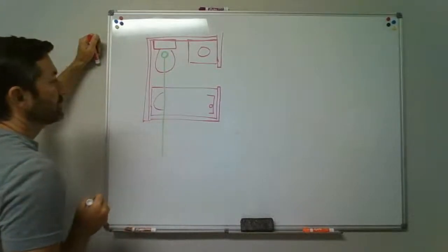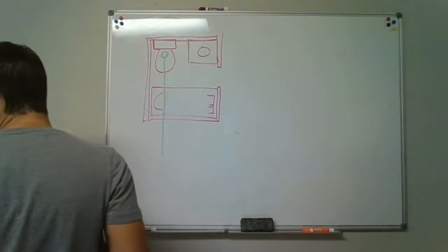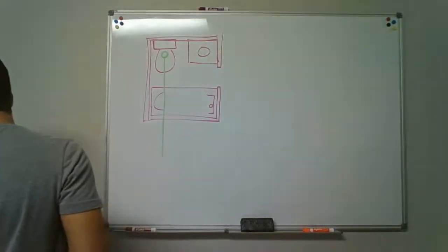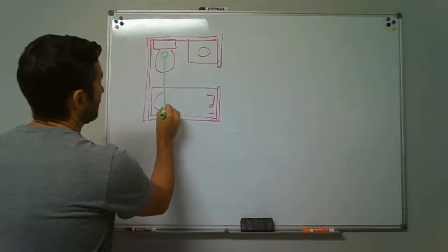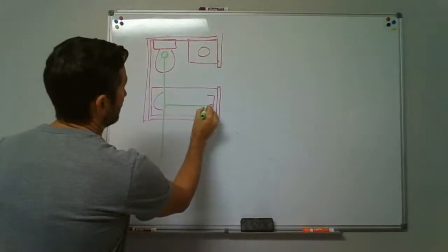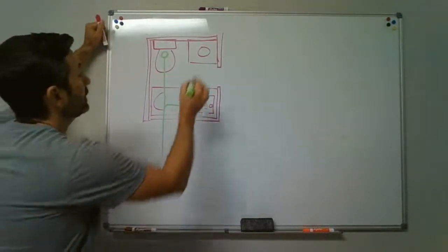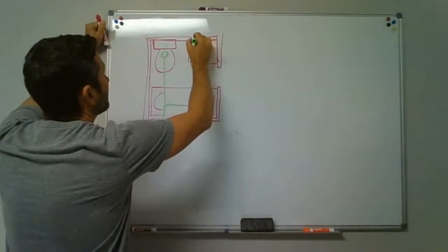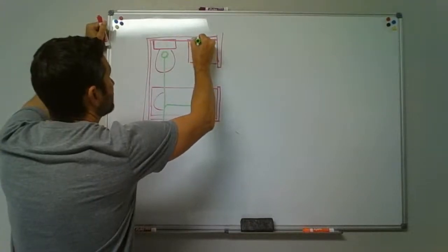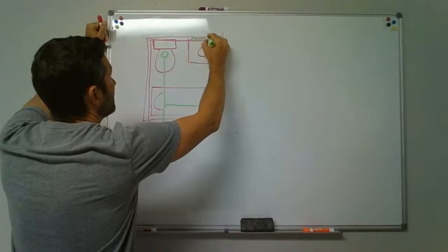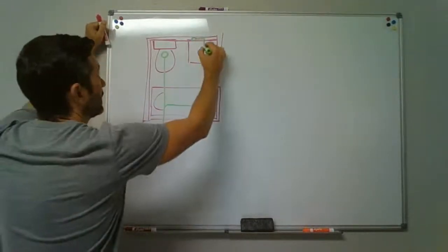Then in order to wet vent this, they'll start to get into as far as making sure how to do it a little bit later on. But basically we've got to always put the vent. There's always going to be a vent. The individual vent's going to be up on the sink portion. Okay.